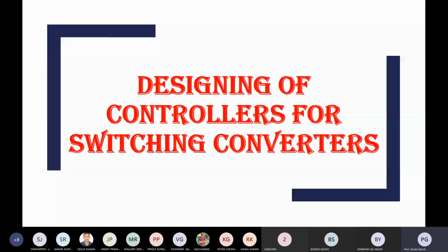That is normally known as identification. In the terminology of control systems, it is called system identification. System identification is important to find out the gradient of the system dynamics in open loop. If you get that gradient from open loop, then you can go for the control design. Any of the control designs.